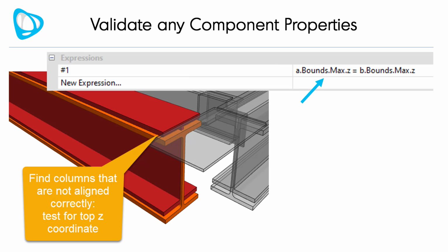The last rule that we're going to look into, and there are others that we're not going to cover in this tutorial, but these are the three primary ones I wanted to go over. So this is where you're checking the matching design intents between two components and two models based on an expression that you write. One of the things Visicon is most known for is the flexibility with which you can manipulate and work with all of the component variables and express their behavior in terms of these expressions. We've extended that now to allow you to write expressions that are in terms of the components in Model 1 against Model 2, or in this case, Model A versus Model B.